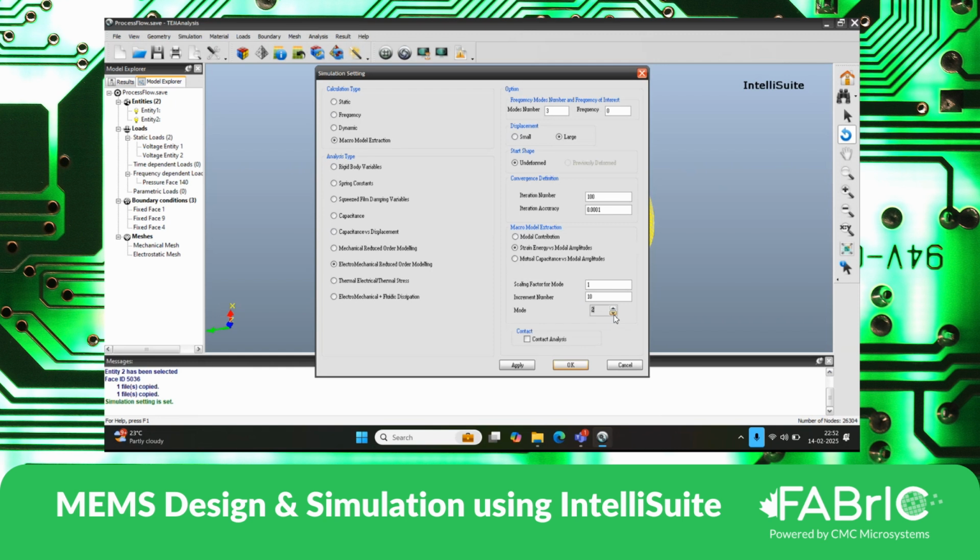Let me show you. For mode 1, if the scale factor is say 0.1 and the increment number can be 10. For mode 2, I can set 0.2. I can set these values based on the modal contribution that has been extracted.